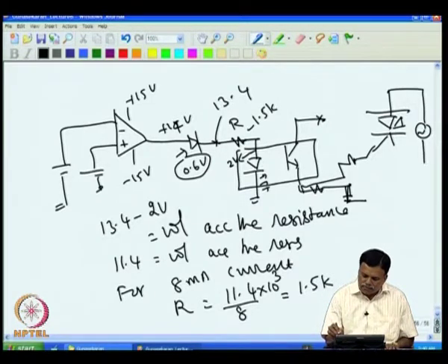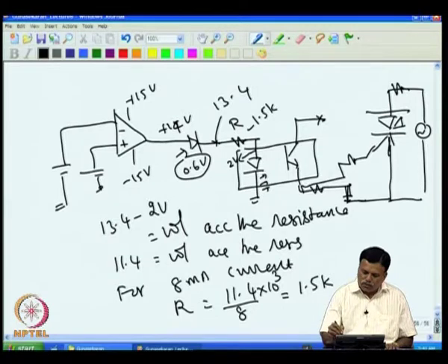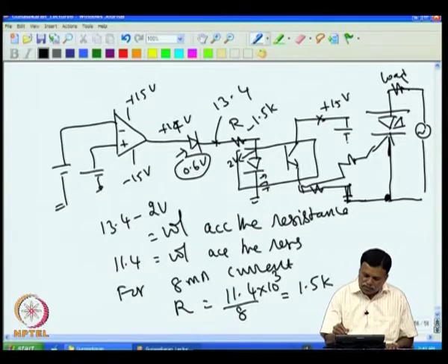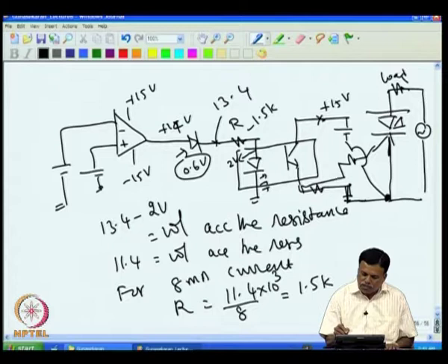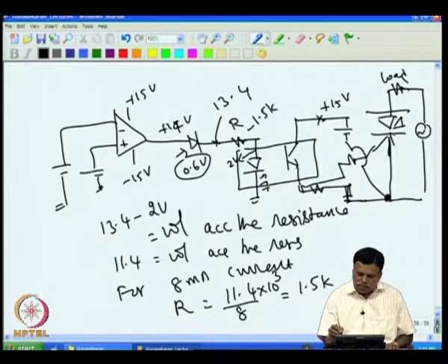So, you have an AC current here and then the load connected here, and that is connected at this point. So, that is the load. AC you have and the current goes through this. Whenever the LED glows, this is supposed to have an isolated supply plus 15, and the 0 of the plus 15 is supposed to be here. So, this supply is connected between this point and this point. Essentially when the LED glows, this conducts and this voltage goes high and that fires the gate of the triac. Whenever the LED is off, this will come to 0 and the triac will not fire. Now, this is a very rudimentary circuit.